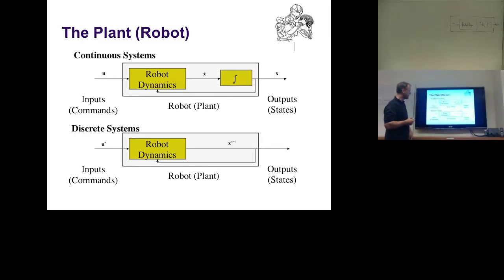Now, continuous systems means we're doing continuous time. In discrete systems, we do time steps, delta t, which is much more natural for what's going to happen on a digital computer when you implement it, since you usually have to run things off a clock. The digital computer, in the end, is not a continuous machine, although it can approximate continuous differential equations pretty well if you discretize the time step small enough.